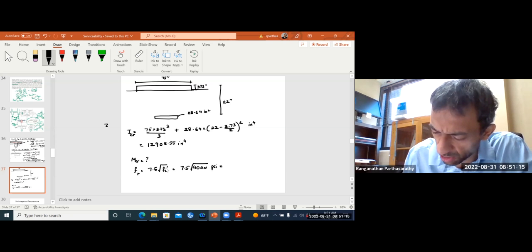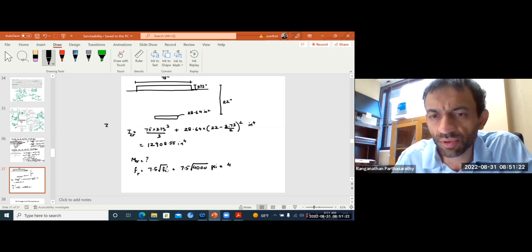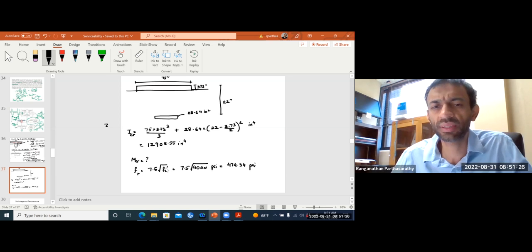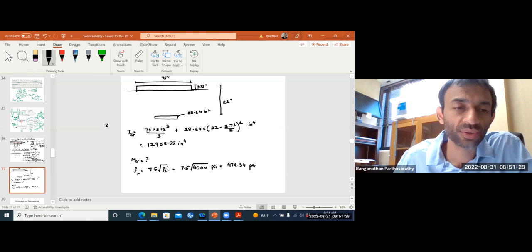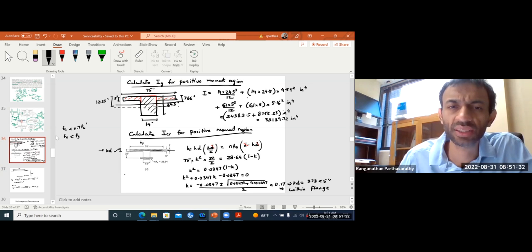How much is that? 474.34 psi. Okay, so you see this here is your Ig. This is the stress that you see in the bottommost tension fiber.